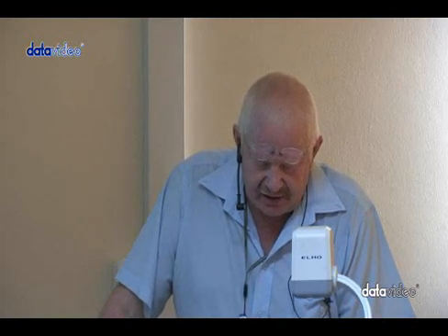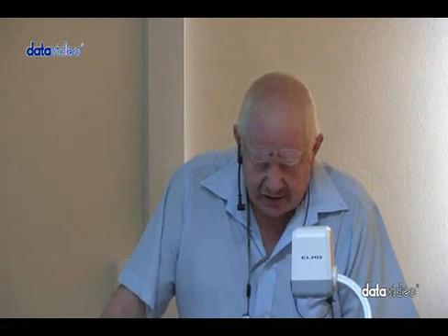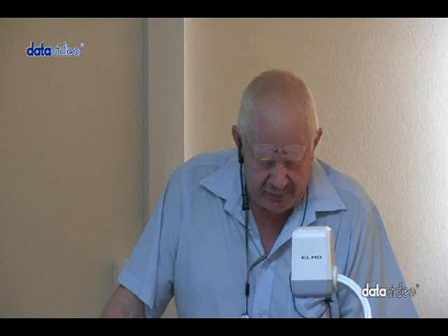Anyway, just to remind you again, what is biasing? Let's read there. The biasing of a transistor is purely a DC operation. The purpose of biasing is to establish a Q point about which variations in current and voltage can occur in response to an AC input signal. In applications where small signal voltages must be amplified, such as from an antenna or a microphone, variations about the Q point are relatively small. Amplifiers designed to handle these small AC signals are often referred to as small signal amplifiers.